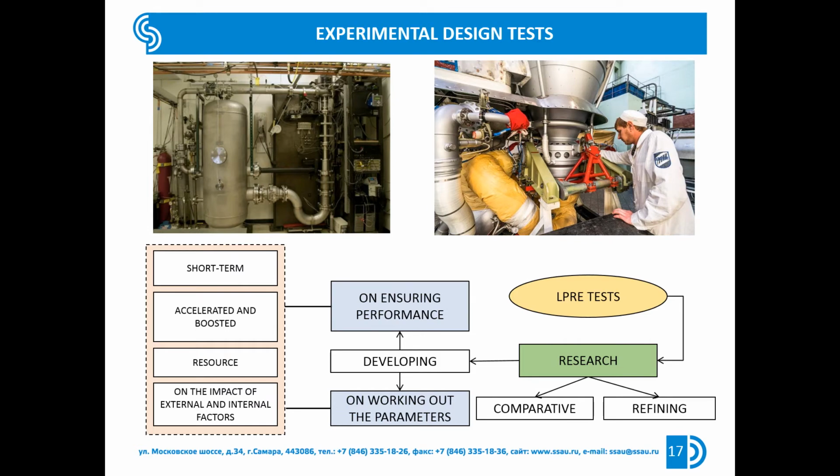The full-size liquid propellant rocket engine development tests are also necessary for final testing of the combustion chamber and gas generator, as a result of which the parameters of the turbopump unit are also refined and the design of the unit is improved. The work to ensure a reliable launch of a newly built liquid propellant rocket engine, including at high altitude, and its shutdown to ensure the safety of the liquid propellant rocket engine after shutdown and the specified value of the LPRE after effect pulse are extremely important and complex. To test the effects of weightlessness on the launch process, flying laboratories based on specially equipped aircraft are used.